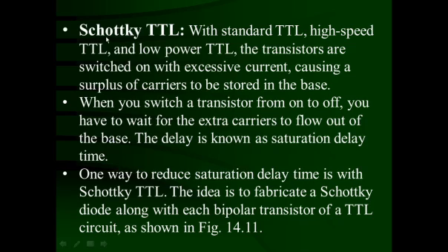Now the fourth type is the Schottky TTL. Schottky is the name of the scientist who invented this one. That's why it is called Schottky TTL. With a standard TTL, high speed TTL and low power TTL, the transistors are switched on with excessive current, causing a surplus of carriers to be stored in the base.